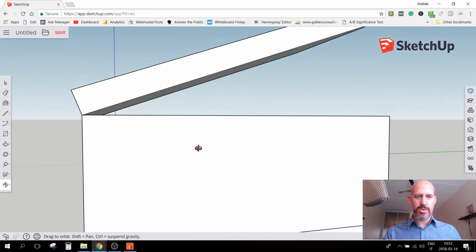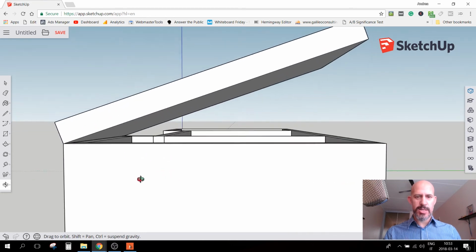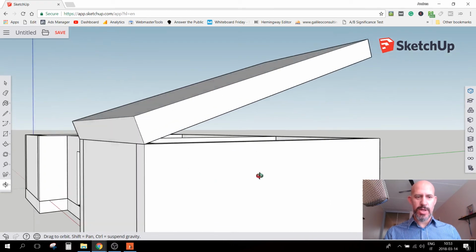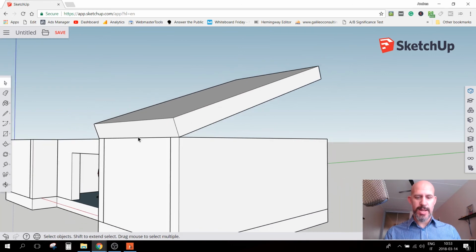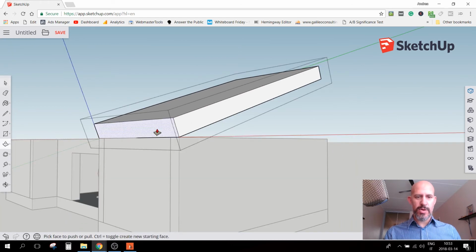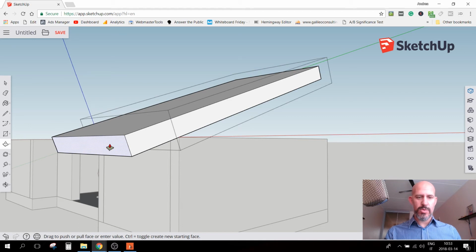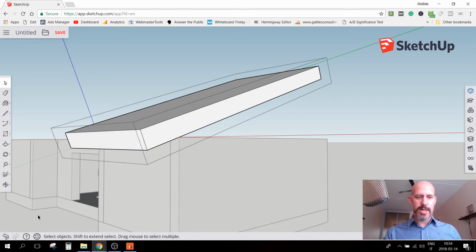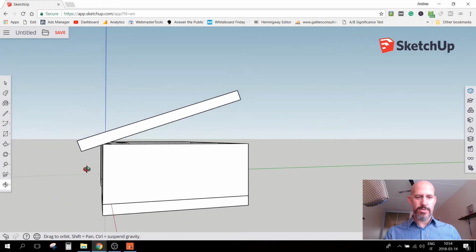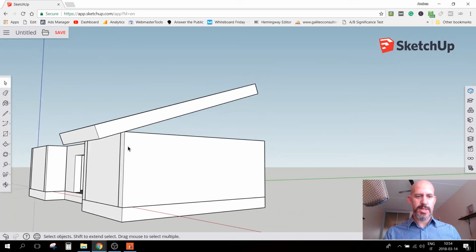So one thing we could do to adjust a little bit the roof situation, because look what happens if I now want to have an overhang here, like a 900 millimeters overhang, this looks awful. Look how thick it is. So you don't want it this thick.